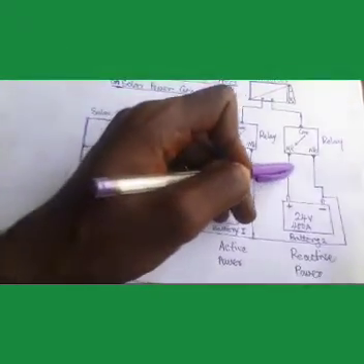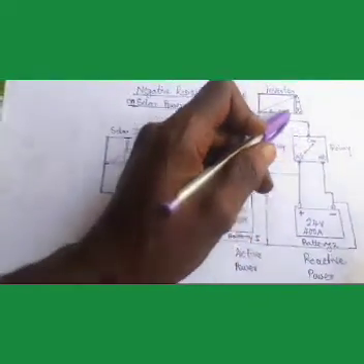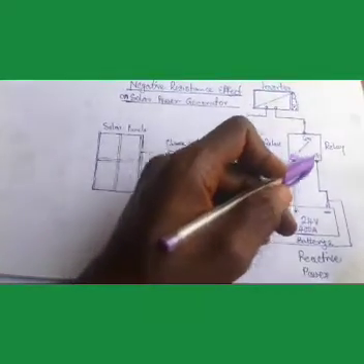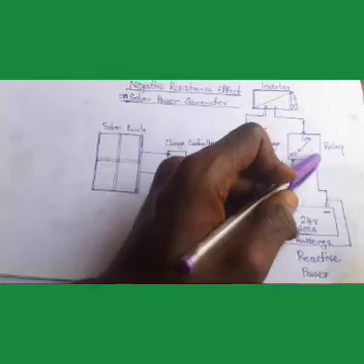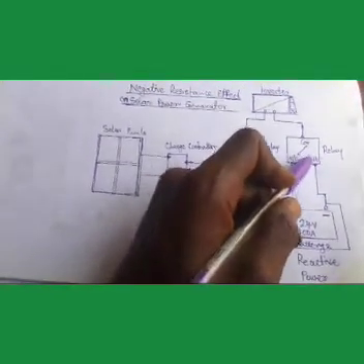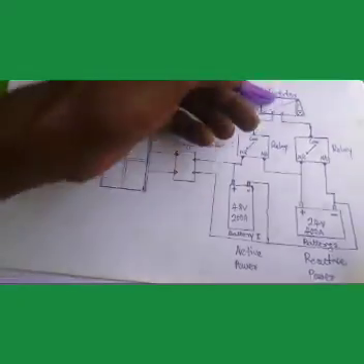Going here, it is now to the positive of the second battery. And for the second relay, what happens there is the negative terminal. As soon as the relays are energized, this moves to the normally open, and it is connected to the negative side of the second battery, and this relay and this inverter are also working.